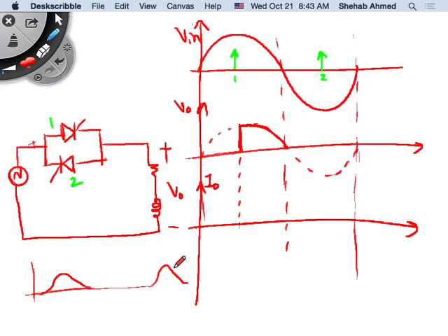So for the full-wave rectifier, it was a continuous current. Remember, as soon as we had full-wave RL case, it was continuous current, right? So for the half-wave, we had current waveforms that look like this. And here we will have exactly the same shape waveforms, because I'm applying the same thing. Here I'm taking my sinusoidal voltage and applying it to my output.